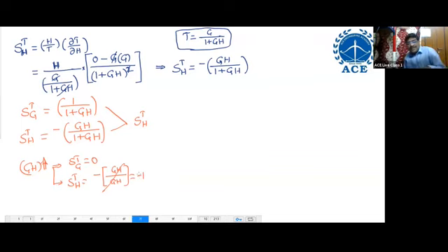The variations are what you have to see here, so sign is not important. It shows that the variations in the output have a 180 degree phase shift, that's all. So almost STH is 1, meaning 100% sensitive, like an open loop system. You should not see the sign, you should see the value.